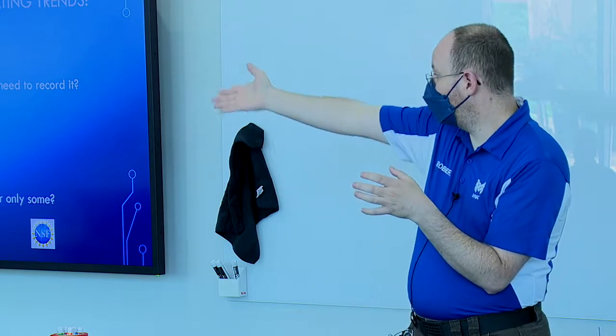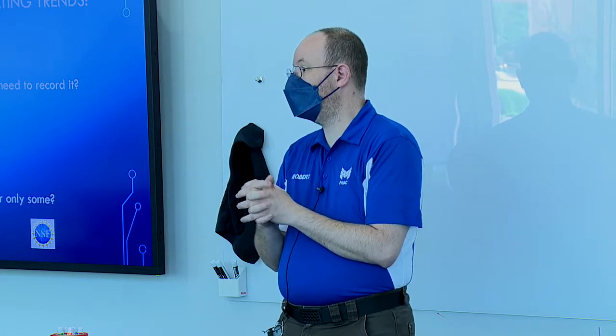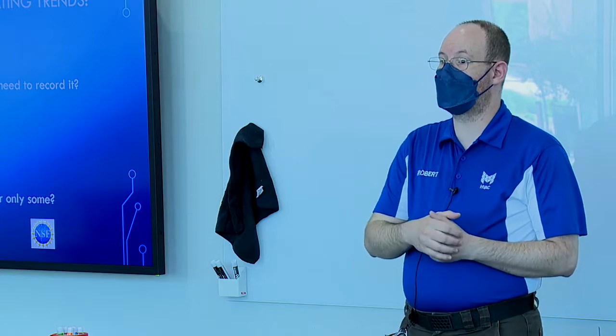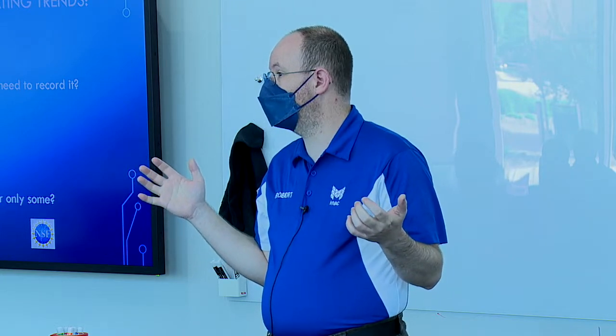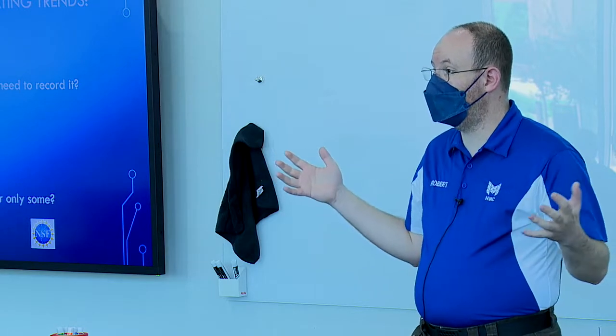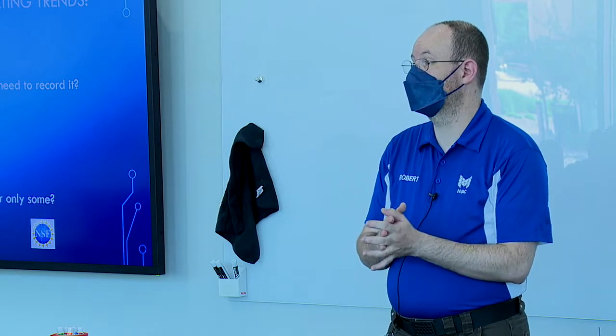So if your room temperature is fairly stable, it's only changing 1/10 of a degree every minute, maybe 5 minutes is good enough. When we see a 1/2 a degree swing, that's pretty close, right? Is it a discharge air temperature that can change literally from maximum to minimum in the amount of time it takes to stroke the hot water valve open? 90 seconds on average. Maybe 10 seconds if it's a pneumatic valve. Do we need to log that every minute or faster?